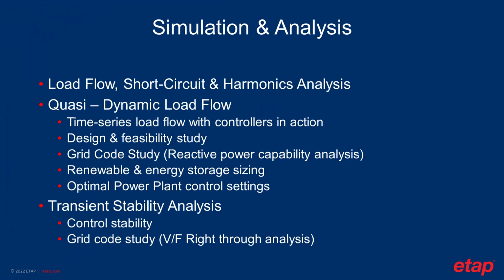For a renewable power plant, when we are using the time domain load flow, most of the time there are controller actions. And for that purpose, ETAP offers quasi-dynamic load flow to consider the operation of the controllers within the simulation environment. And some of the benefits that quasi-dynamic load flow offers are that it enables the design and feasibility studies, investigating the grid code capability of a renewable power plant, sizing energy storage and renewable assets in a system, and figuring out and tuning the optimal power plant control settings.